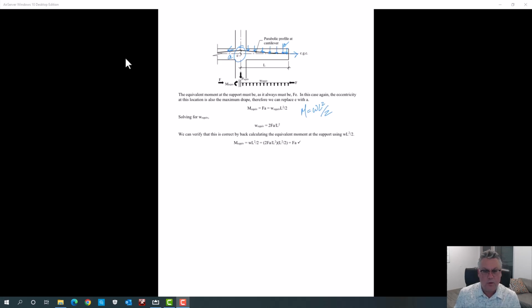Parabolic profiles will give a constant uniform load, and all of those loads are equivalent loads. They are being counteracted between the concrete and the tendon. They offset each other to create a grand total of nothing. But what's useful about them is if we place them on the concrete only, we will get an equivalent moment diagram, a primary pre-stress moment diagram, that at every location is equal to the force times the eccentricity at that location. So that was the whole point. Come up with a load that gives us what we really already could have calculated just by taking F times E at every location.